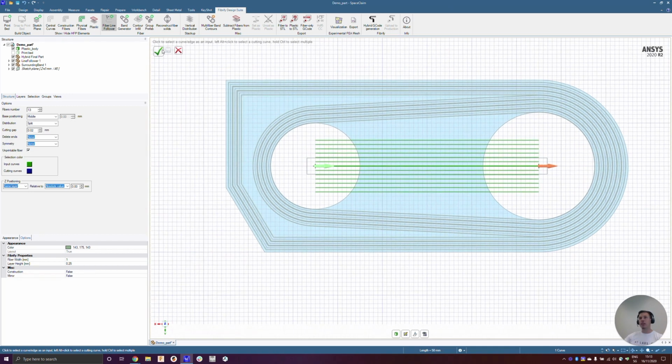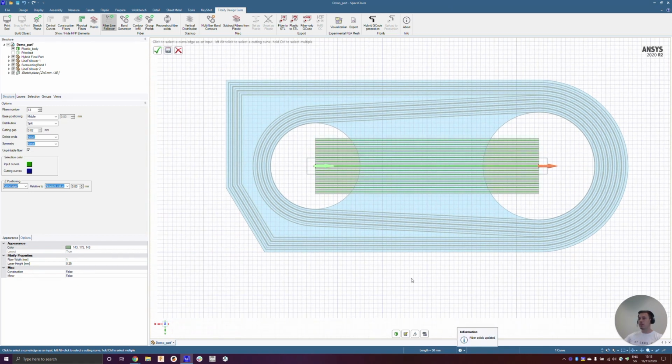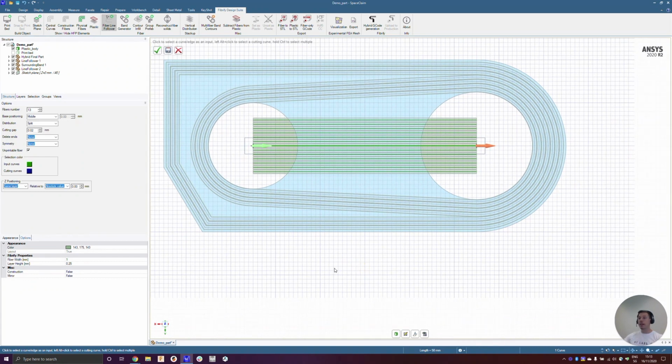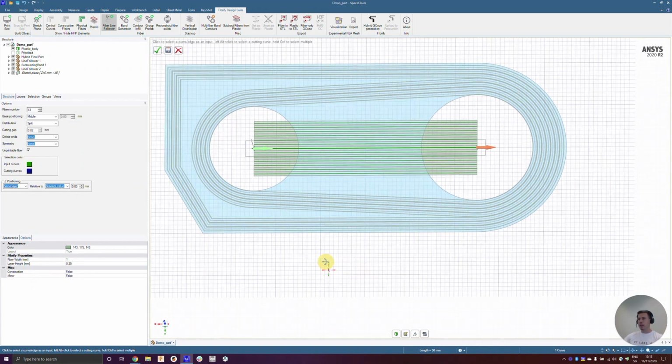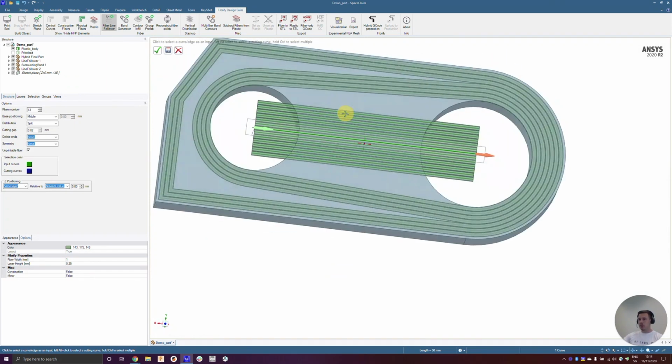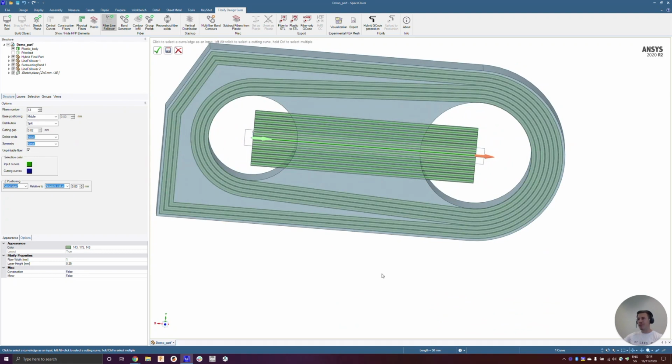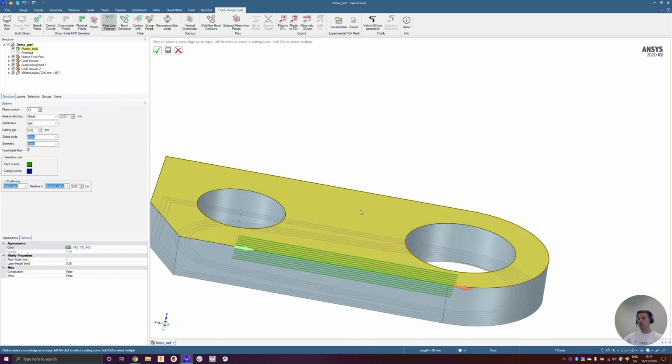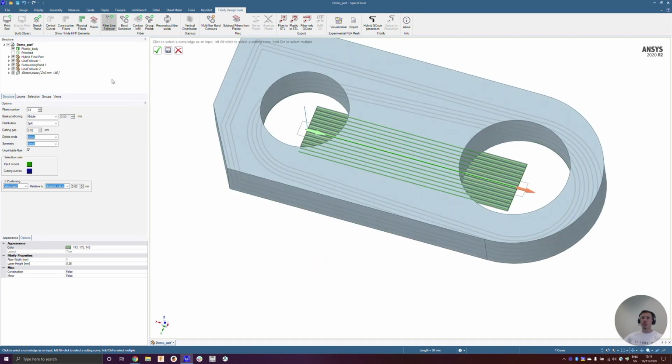When we go now ahead and create these fibers, you can see that we are sticking out of our model geometry. So when we go into 3D mode again, by pressing D, for example, on your keyboard, we can see, as I just said, these fibers are just a little bit too long. So we have to actually go back and make some changes. And to do so, what you can do is, as long as the fiber line follower tool is still selected, we can select an already created line follower. In our case, the line follower 2, for example.